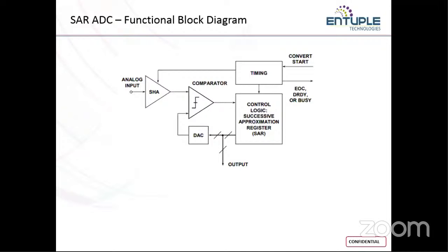Okay, so for building a successive approximation register, we had made use of D flip-flop. In terms of ORCAD PSpice, we made use of the IC number 7474, whereas in Cadence, we made use of a set reset based D flip-flop with a drive strength 1.